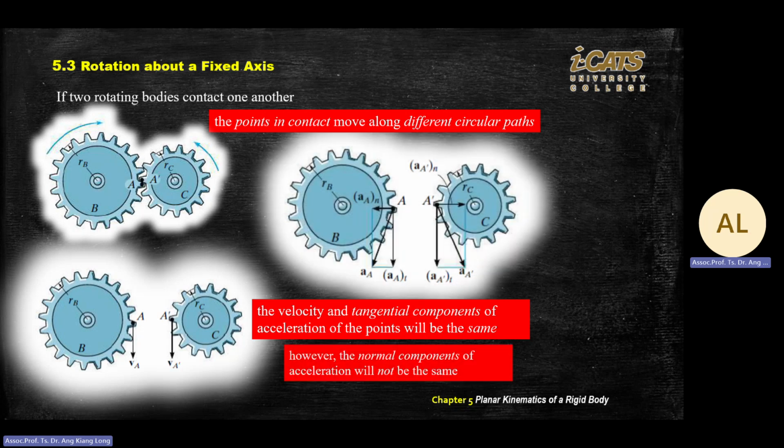What I want to show is the vector diagram for velocity, which is in the left hand corner, this one. The velocity goes down with the different circular motions, and from the V you can change to acceleration, because you know that you have AT and AN. AT always follows the direction of your velocity. If you look at gear B, AT goes down, and AN always points inside the circle. That's why for B, your AN is towards the inside, to the left. And once you have AN and AT, you can draw the resultant pointing towards the left hand side.